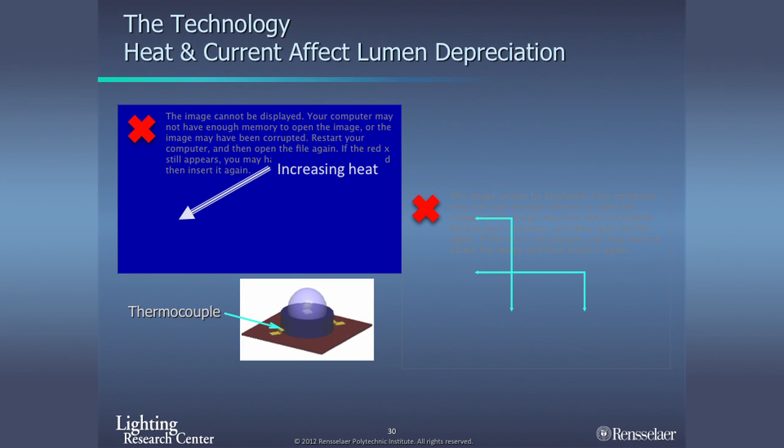If you overheat these LEDs, they will diminish in life dramatically. LED manufacturers set a maximum junction temperature, and typically that's relatively high. It's about 90 degrees C, and we'll see some actual applications where maybe we actually get to that. For every 1 or 2 degrees over that, you could actually be cutting the life of that LED in half. So you have to be careful that when you install these LEDs, you put them up in your ceiling plenum or wherever you're going to put them, you have to think about the thermal conditions there.